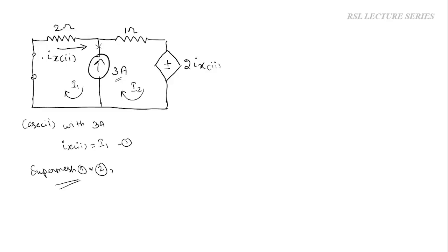Here we do not have a voltage source. Here we have one voltage source. This is a current dependent voltage source only. So the current direction I2, we have assumed it to be flowing from positive to negative. So this is considered as voltage drop. In this case, we do not have voltage rise. So now we have to write down the voltage drops.